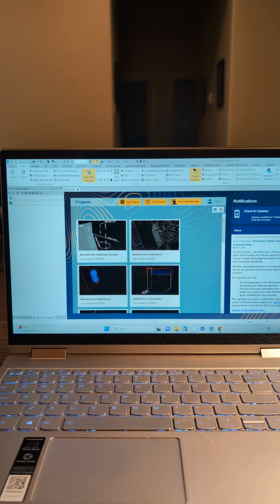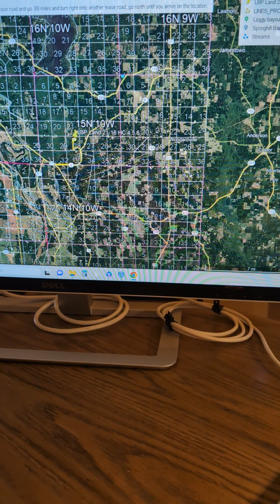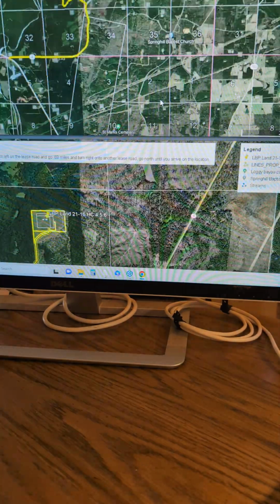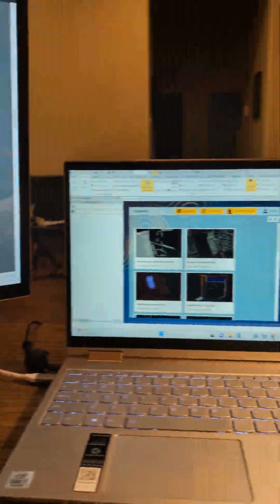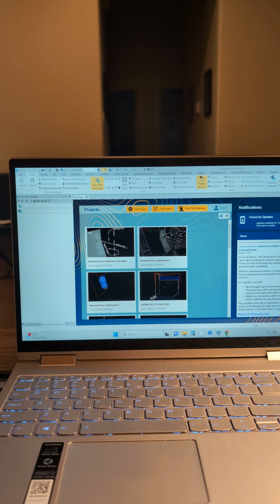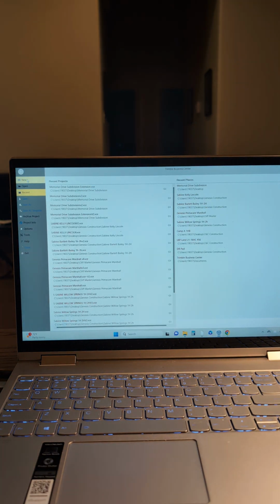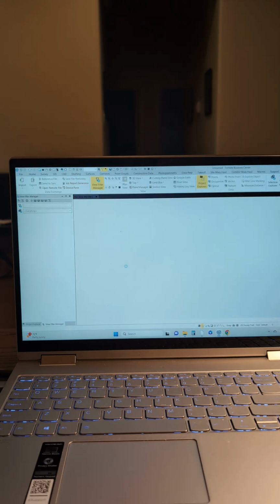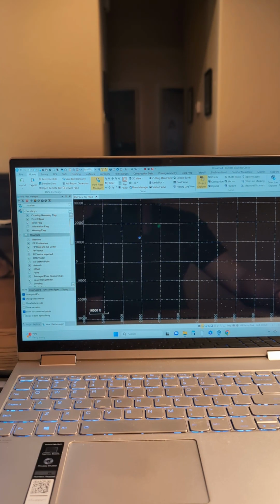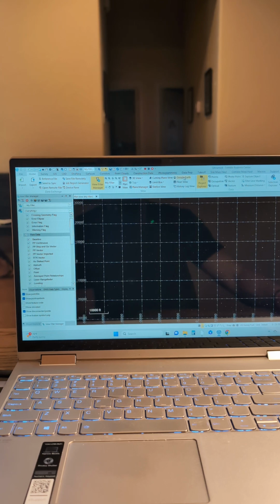You open up Business Center and you're going to start a new project. Generally, you have a set of drawings that you're going to import and you're going to draw from there. But first, you need to open up TBC. So you go to File, New, US Survey Feet, checked, okay. And you're here, you're at the open project. It's not saved, it's unnamed.